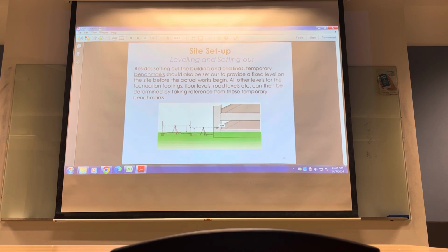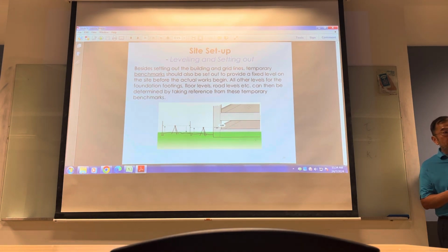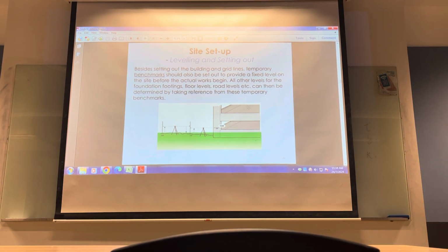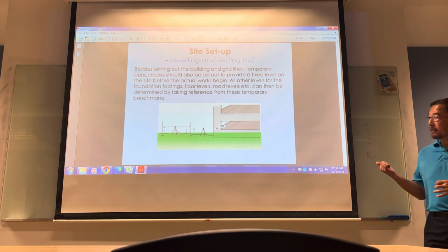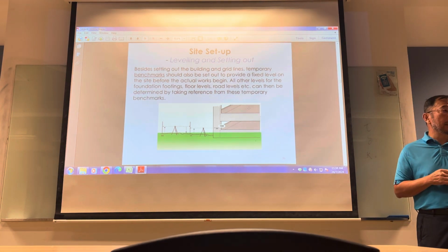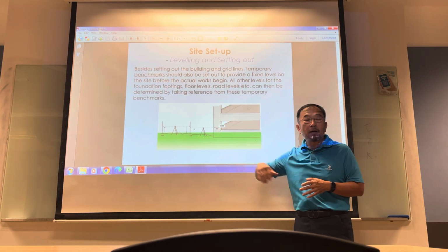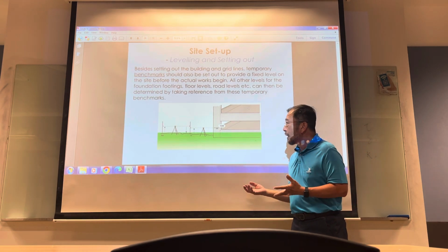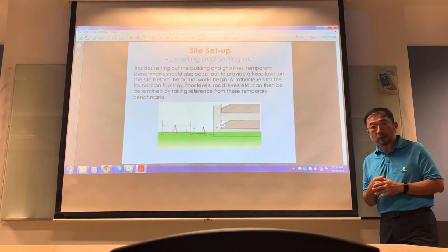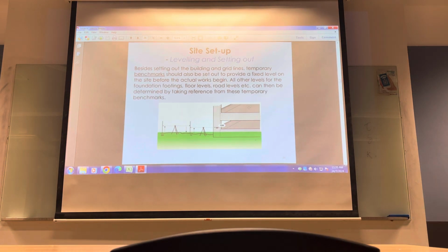Surveying is a process in civil engineering to establish site information, site layout, to do site data. Leveling is the simplest operation in surveying. Leveling means to know the level of the ground, to establish the ground of your construction, of your structure, so that you can build them according to the design. There are references, which is called temporary benchmark, TBM.